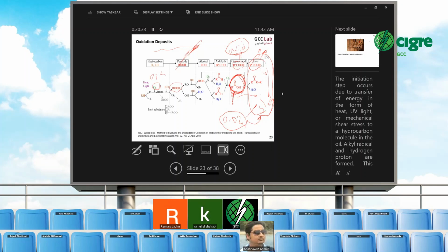Okay. Thank you. Regarding the DGA of cable box, we see transformer main tank and cable box. DGA, we have standard limits in IEC 60599. But is there any limit available for transformer cable boxes? Because in IEC 60599, there is no specific information about cable boxes. Exactly.